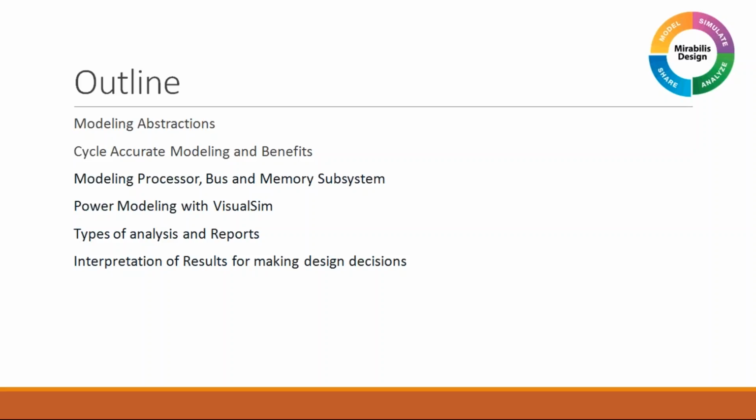I'm going to walk you through some demo examples in which we're going to look at cycle-accurate level libraries for these different blocks, and to be able to understand or generate different types of reports and analysis and make design decisions. For example, selecting the resource clock speeds, or designing a memory subsystem, or optimizing your memory subsystem to achieve better performance versus power trade-off scenarios.